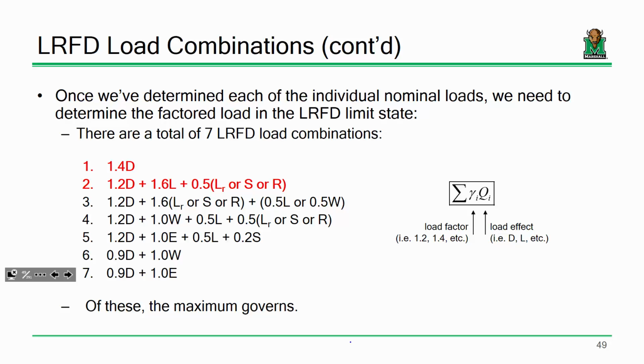So you've got a dip in the roof where there's an excess of water, right? What does that dip in the roof do? It allows for more water. More water means it's going to deform more, which allows for more water, which means it's going to deform more, which allows for more water. See how it kind of builds on itself? That's called ponding. Usually, though, if you detail your roof appropriately, you never have to worry about it. So I don't want to say it's ignored, but folks like me really don't need to cover it, because as long as you're detailing your roof appropriately, it shouldn't happen. But it's just something I wanted you to be made aware of.